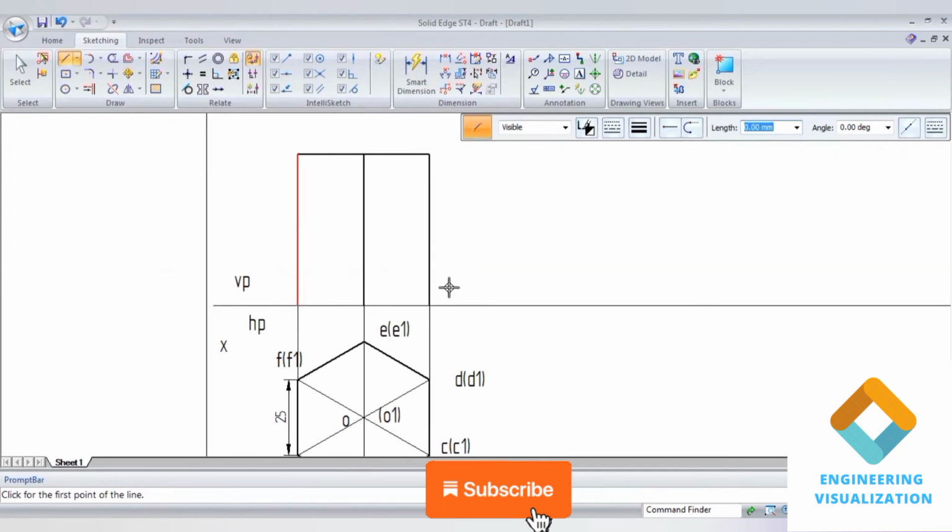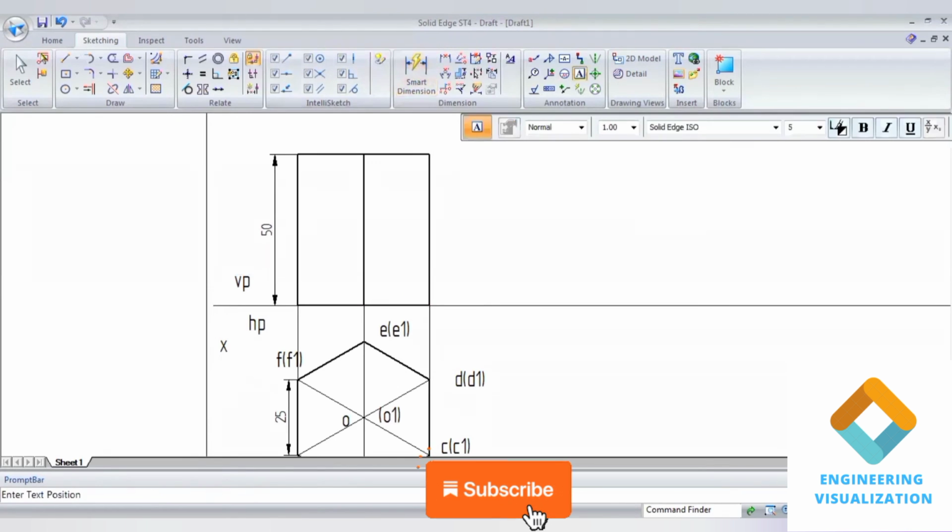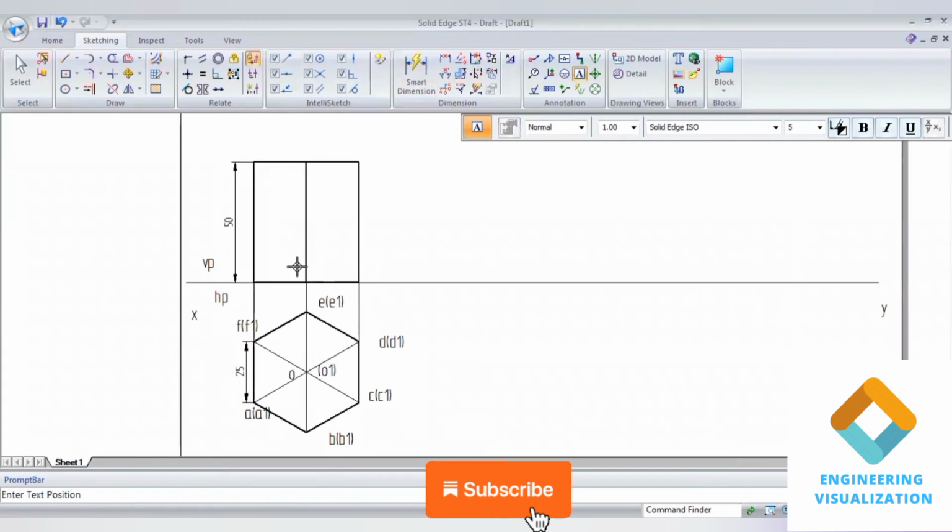Now write the front view notations, marking which are visible from the front view. From the front view, A dash, B dash and C dash are visible, and D dash, E dash and F dash are not visible. Not visible means we should write them within brackets. In the same way we write for the bottom face also.